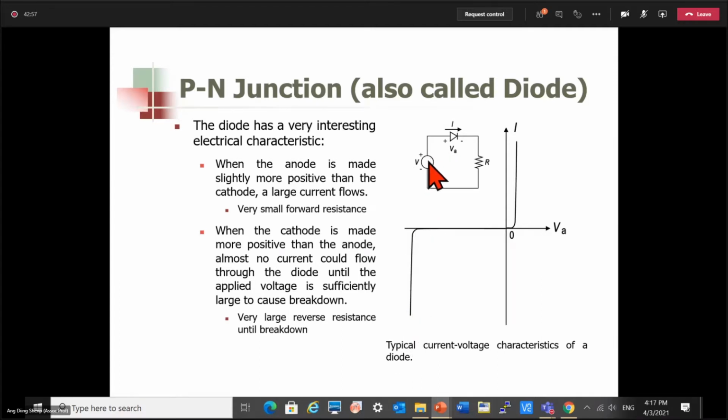But this voltage at which a large current flows is much larger than in the positive case. The voltage here at which a large current can flow typically is on the order of tens of volts or even hundreds or thousands of volts. On the other hand, a small positive voltage is just enough to turn on the diode, and this voltage is actually less than 1 volt.